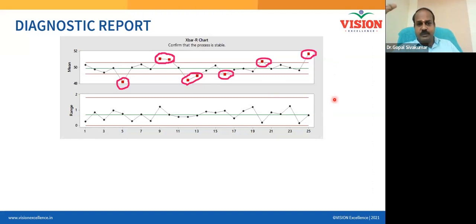That's called normal performance. Normal means nobody finds even a single chance to comment about how the process is performing, and it's just performing normally. Everything is happening on its own according to the process. We can't judge anything. Any kind of pattern or cyclic nature, if that appears, they're all special causes. Special causes not only means seeing points outside the control limit. Sometimes you will be able to detect special causes even if all the points are inside the control limit.